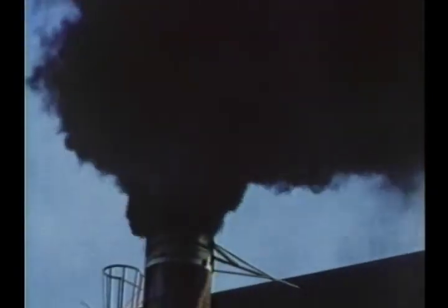As we have seen, a steady flow may become unsteady for certain ranges of flow parameters. The instability takes its energy from the mean flow and the mechanism can be thought of as a selective amplifier, its characteristics governed by flow parameters. Flow instabilities occur everywhere. Smoke from a stack billows. The flow in a river is turbulent. The turbulence is caused by flow instability.